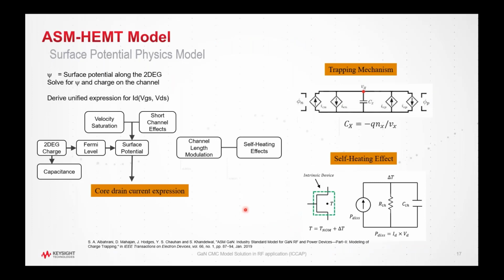The next one is the ASM model. Just like I mentioned, the ASM model solves the Poisson-Boltzmann equations. The equation is quite simple and relates to the surface potential at the source and the drain, where ds represents the difference between them. It has only one equation, but it actually covers below threshold, subthreshold, and above threshold voltage. So this equation pretty much covers all regions of bias.